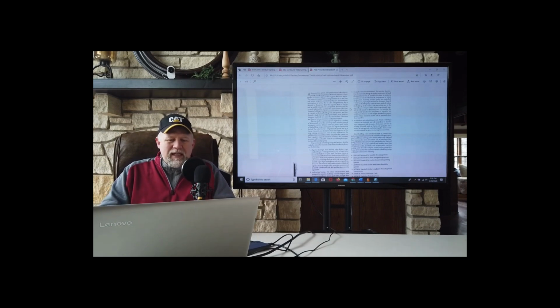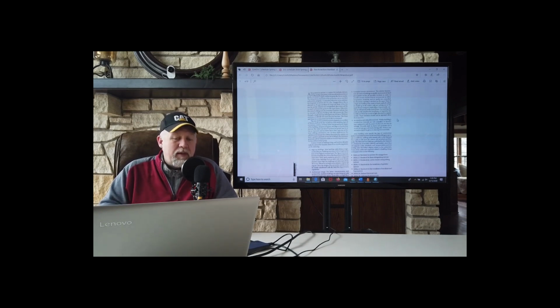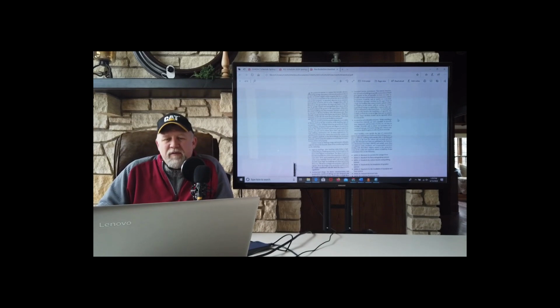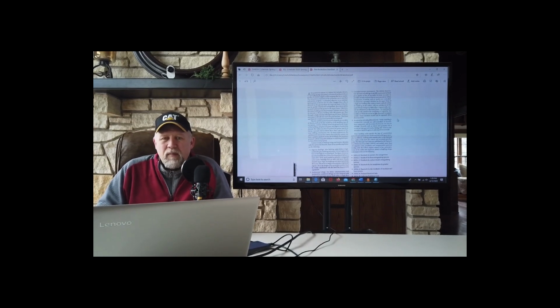Let's get into the definitions and talk about how this affects construction in general, because it drastically affects construction. Fire suppression systems don't add a whole lot of cost to a building. In all seriousness, you can get the bare bones automatic sprinkler system with sprinkler heads done in a building for around $3 a square foot, maybe even a little less.